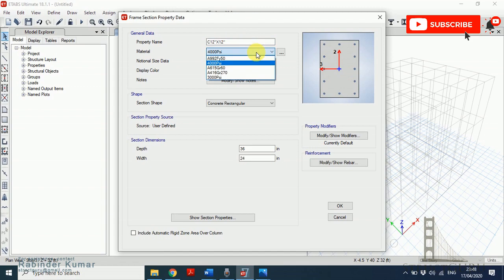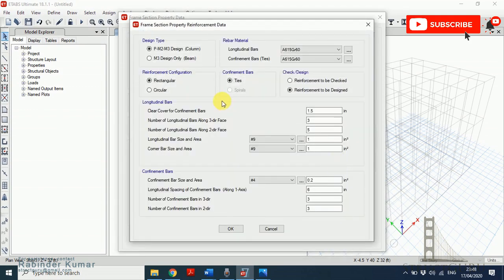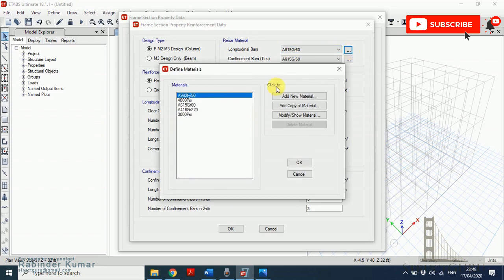I want to keep 4000 psi for my column. So change the dimension here, 12 inch. Go to Modify/Show Rebar. If you are going to define the column, click here, column, longitudinal bars. You can change the type of bars from this section.